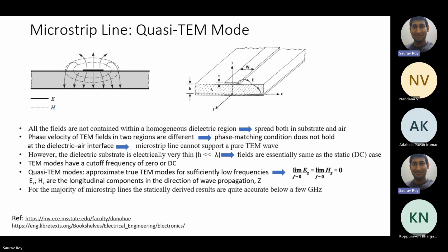And do you know why it is important? Because from modes you can get the electric and magnetic field configurations. You can also see what the dominant modes are. You can calculate the Poynting vector, the power density, as E cross H star. So that's why studying the mode is very vital. This is the most basic, fundamental study you can do in any circuit in electromagnetics.